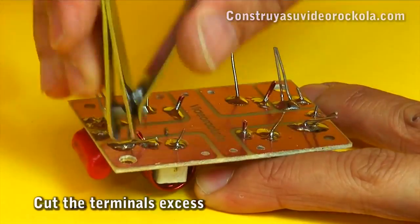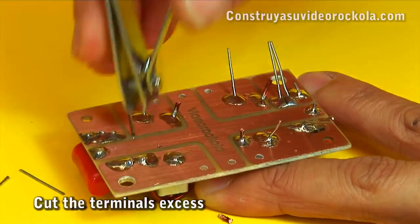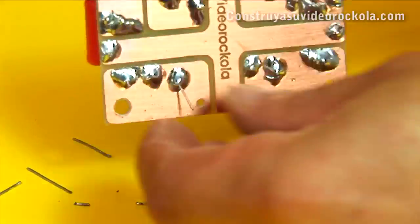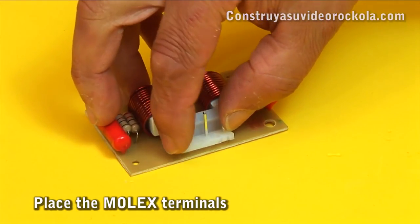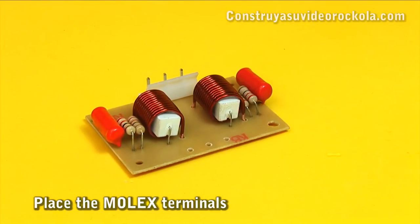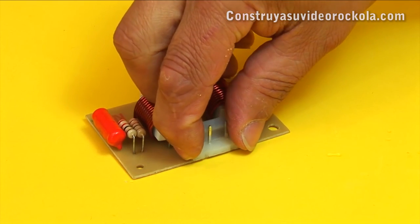With the aid of a nail clipper or a wire cutter, we cut off the surplus of the component terminals. Now, place the 6-pin Molex type terminals, from which we have previously removed the pin in between, and in the opposite direction, so that when installing the circuit, it can only be connected in one direction.